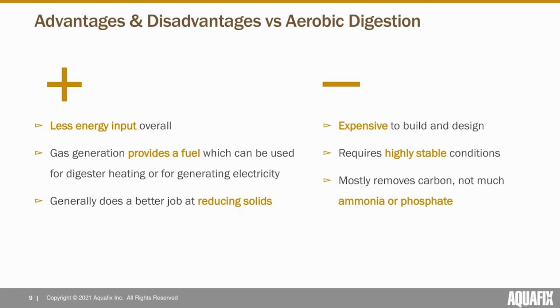But once you start to see mid to larger sized wastewater treatment systems, or you have industrial systems with specialty waste which digests very well anaerobically, usually these are very high strength waste streams, then you tend to prefer an anaerobic digester, assuming you can keep it running stably.